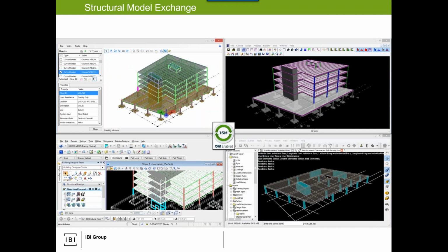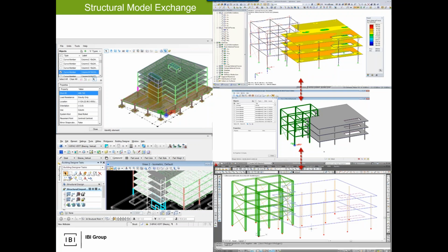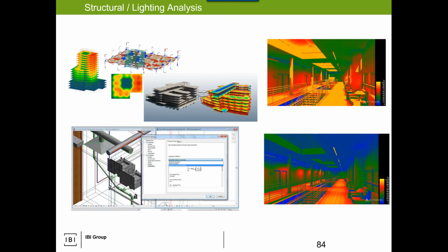The ISM is a Bentley term for an integrated structural model, and it facilitates the exchange of structural data either from Bentley or Autodesk authoring tools. So I can go from Revit through ISM into tools like STAAD and RAM and other Bentley-based analytical software, and we have that flow of data and analysis to and from. So here I'm showing AutoCAD to ISM to an analysis tool and back and forth. And it's the back and forth that's intriguing because oftentimes that's compromised.